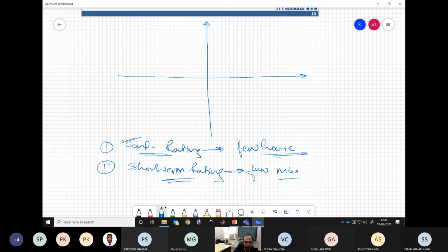Here, the torque or some quantity is taken to an extreme value for some time, and then brought back within the continuous rating. We are not violating the thermal limits, but going a little higher than the regular duty. That is called the short-term rating.